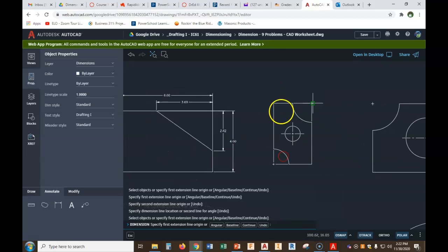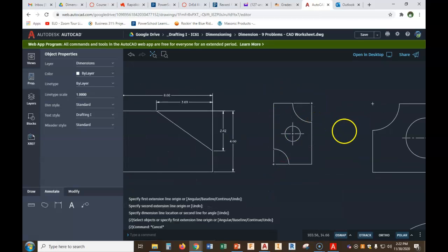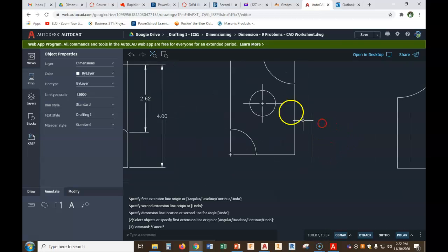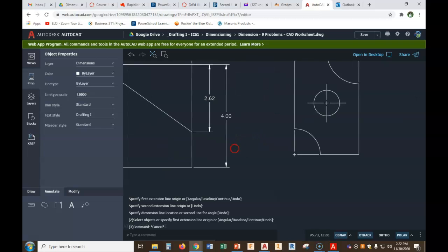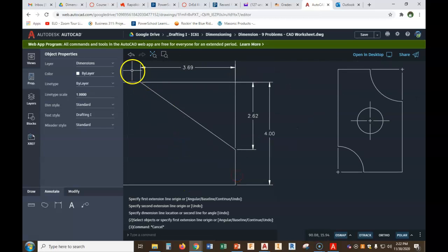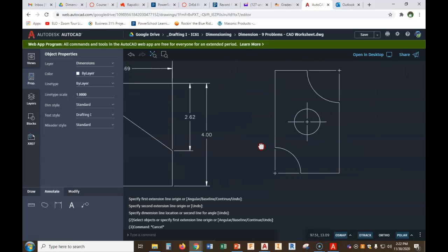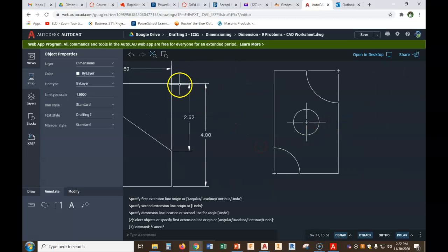All right, how about this one? We've got 2 cutout corners. We've got a hole. This is a little bit different. For a hole, we do want to dimension the center point because that's where the drill bit's going to go, right? So our center lines work for us. Now notice we've always left our little gaps everywhere, right? Everybody agree? A center line becomes an extension line.